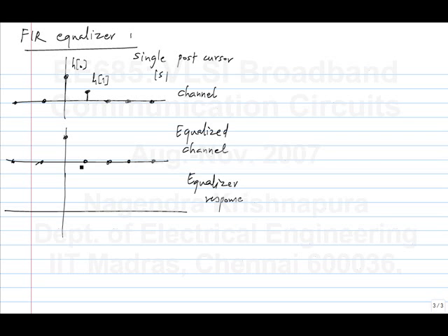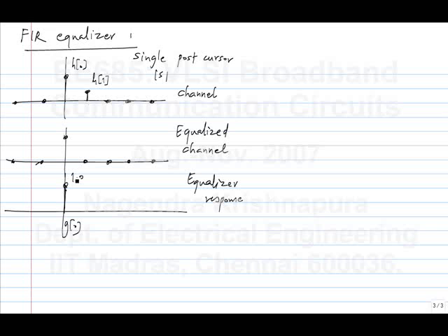He says it has 2 taps. I will weight one of those taps with, let's say, 1 arbitrarily. I can choose the rest of them to be anything I want. So would I put the equalizer tap before or after this? After. Why? This is G of 0. I want a 2 tap response. Would I have G of -1 to be non-zero or G of 1 to be non-zero? G of 1. Why? This 0 basically corresponds to that 1.0 tap. I can have some things before it, I can have things after it. You want to put it here and you want to make it negative.